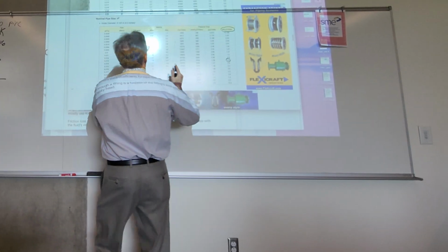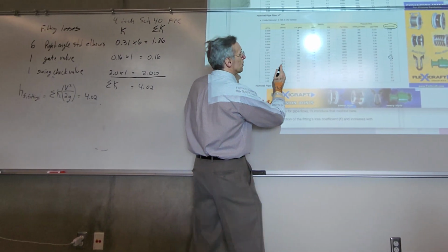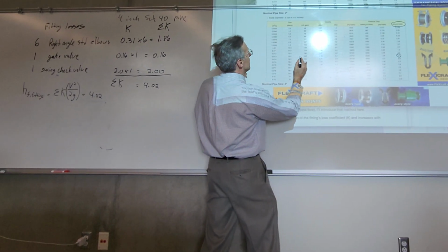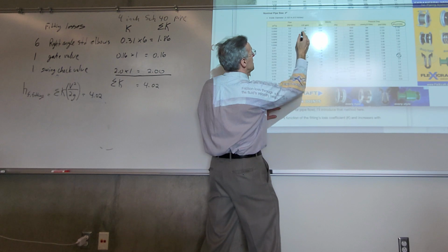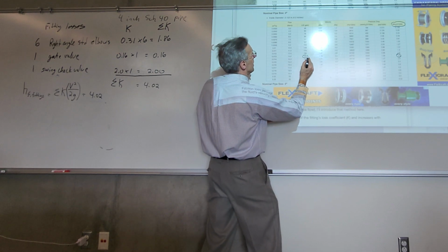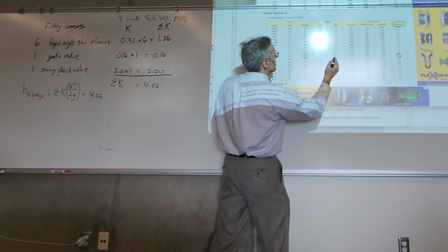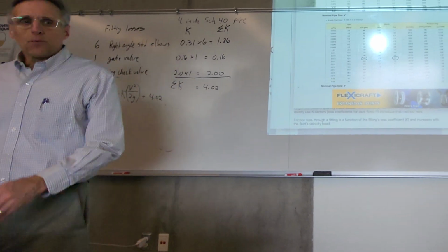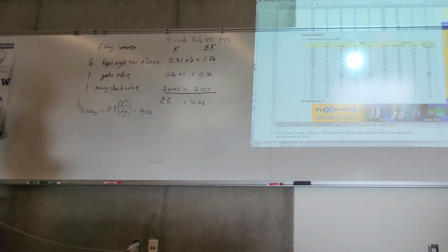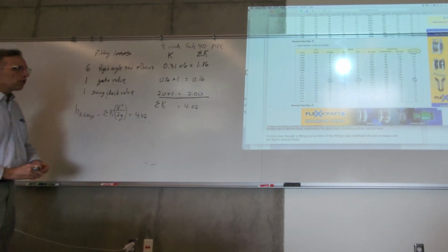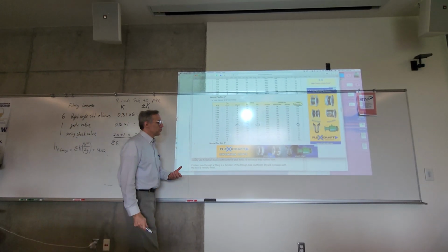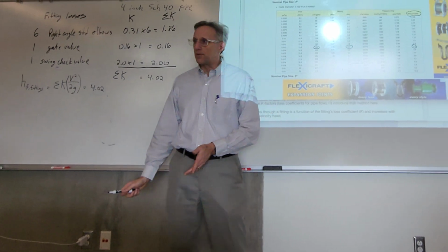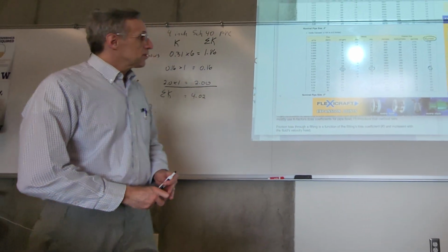The flow rate in GPM is there, and the velocity will be 5.2 feet per second. 4 feet per second is what we're moving towards, but 5.2 is okay; 4 to 6 is good for an HVAC system.